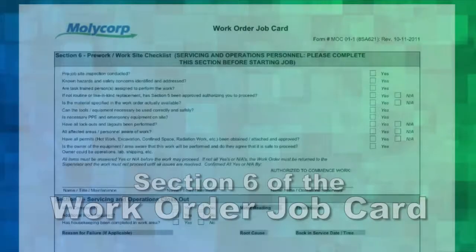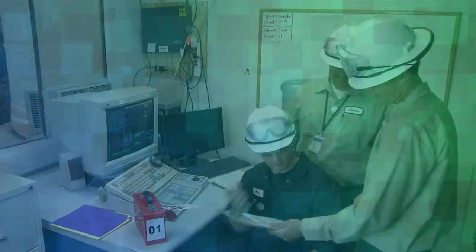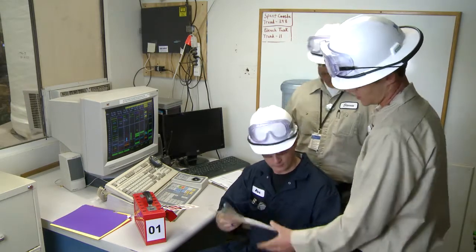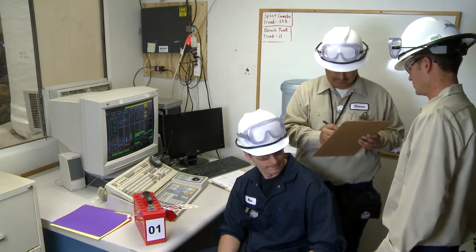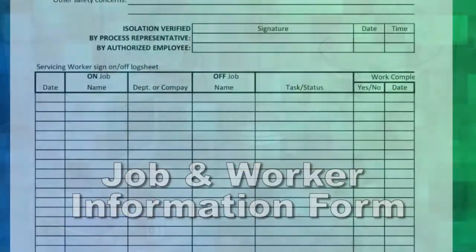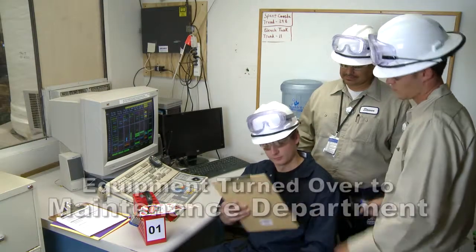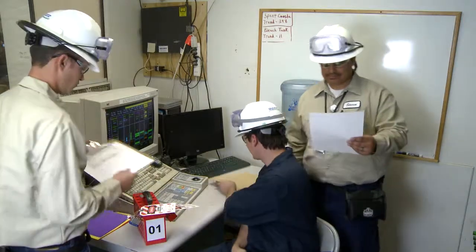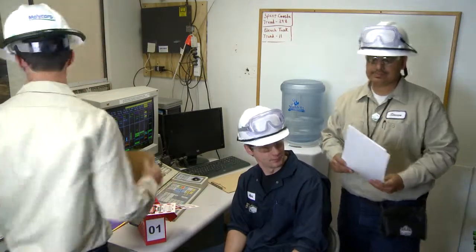The servicing representative fills out Section 6 of the work order job card. The servicing representative, process representative, and authorized employee sign Section 6 of the work order job card. The servicing representative fills in the top line of the LOTO Job and Worker Information Form. With this step, the equipment is turned over from operations to maintenance. Once paperwork is complete, all of it is gathered and kept in the control room for the duration of the job.